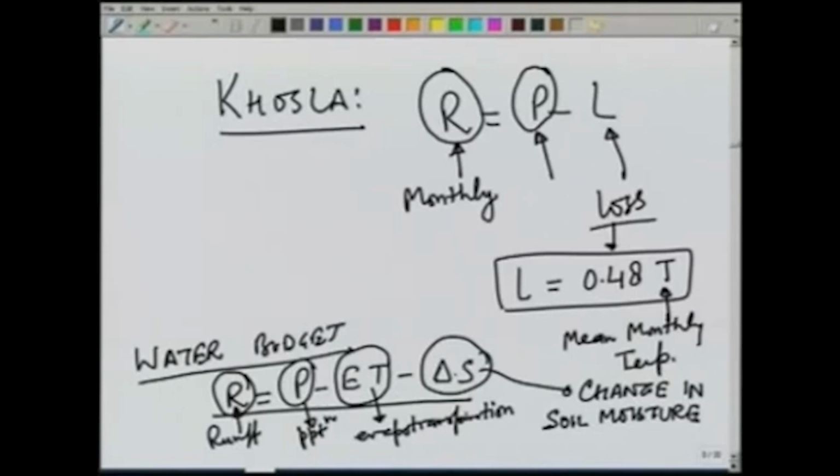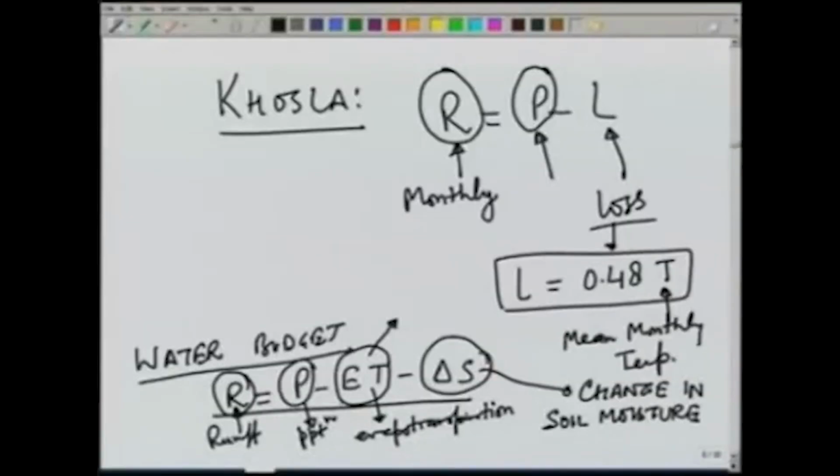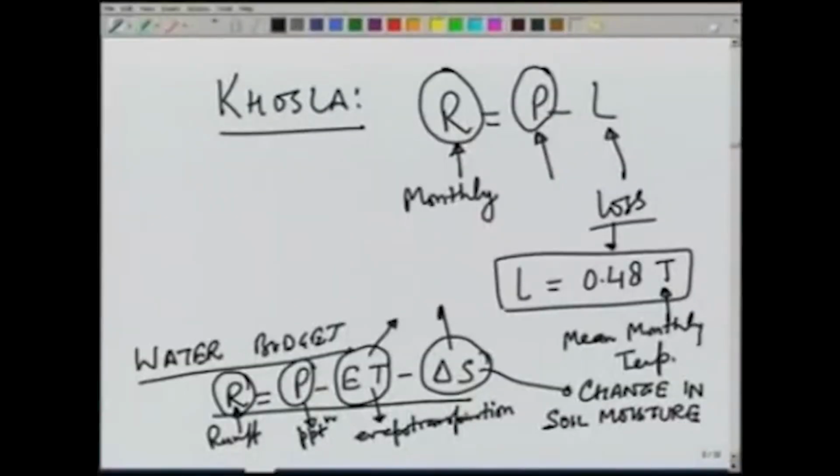But for this model, we need to estimate evapotranspiration. We have seen in some other lectures that evapotranspiration can be obtained from the atmospheric conditions like wind velocity, temperature, and so on. So, all those factors have to be input here to obtain the evapotranspiration, and we can do this water budget modeling over a daily or weekly or monthly time interval. Delta S has to be estimated based on the crop pattern, the crop water requirement, or if soil moisture data is directly available, we can utilize that.